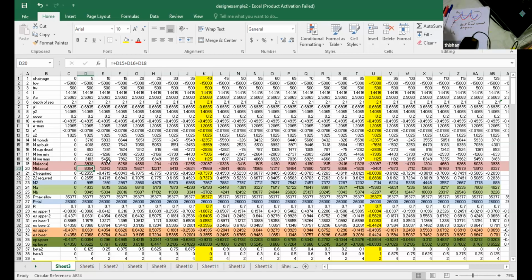After a long period of time, what is applicable is monolithic. And if you look at the direction it's moving, it will start at as-built, which is the lower diagram, and move towards the upper diagram, that is monolithic. So when I want the maximum bending moment effect, that is MB, I would use the lower boundary, because I'm going to get a bigger bending moment.